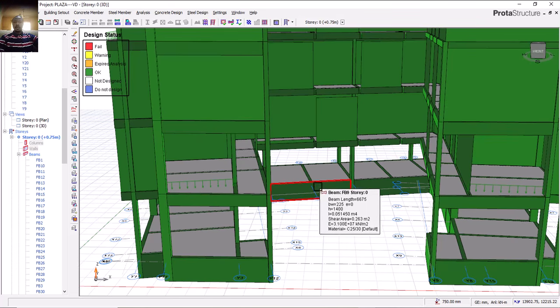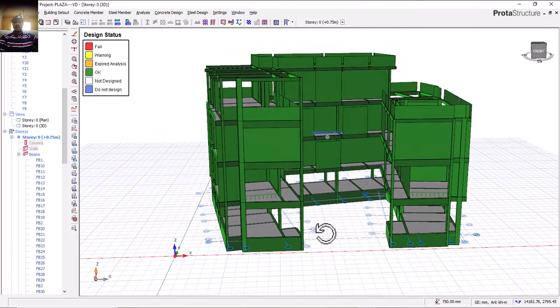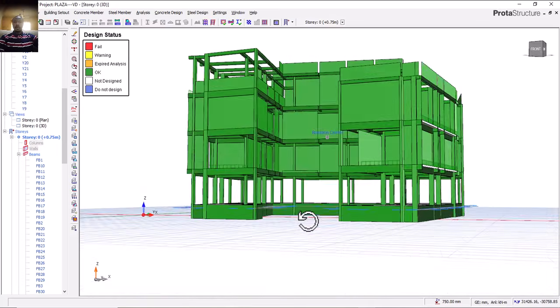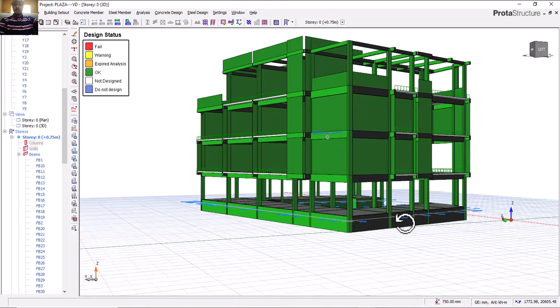So you can now imagine if you had gone to use a strip, and we know that the maximum beam for strip is 950. Automatically, it would not have worked, even though the strips pass the design, but the beams would not have passed the design, which might still prompt us to go ahead and use our beam raft. Do you get it now? So that is that. You can now see the structure, how it has been successfully designed.